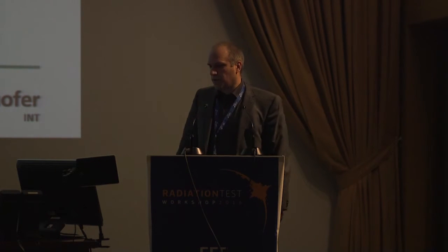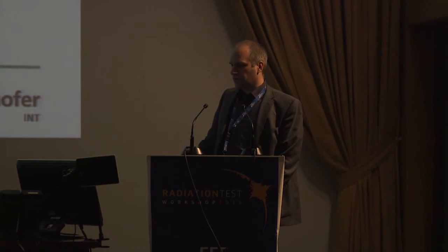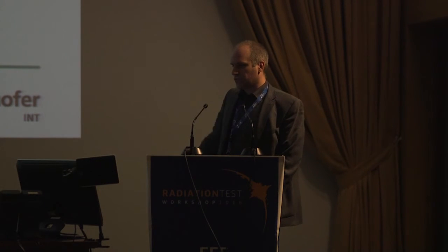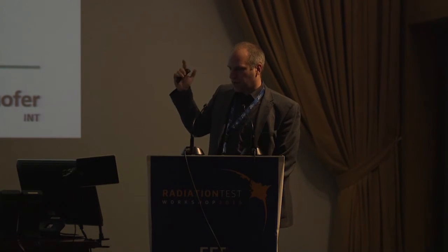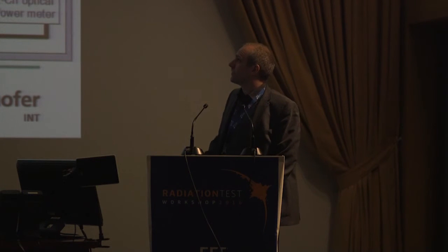Testing is usually done online, not in step stress, and it needs highly stable equipment because during the measurement you see every disturbance. So usually you should irradiate exclusively and then not do any breaks or put something in and out of your facility during the irradiation of the optical fibers.